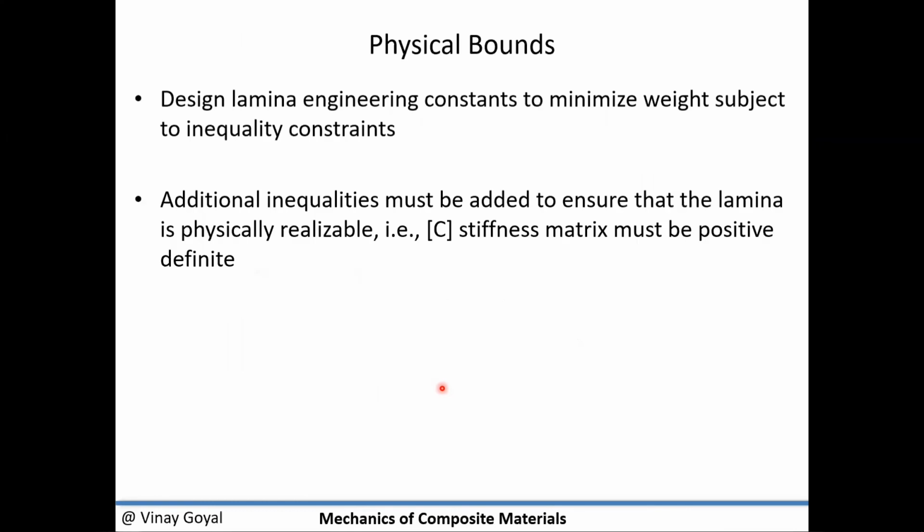What about lamina design? What if I want to design a lamina? I want to come up with a new material system. And Dr. Scott Peck, very well known in the area, has written a paper. But what if I want to do that? I want to come up with this design lamina engineering constants to minimize weight. So that means coming up with a new fabric system, a new matrix system, something innovative that helps you minimize weight. So before doing this, it's important to understand the inequalities that must be added to ensure that the lamina you're working on is physically